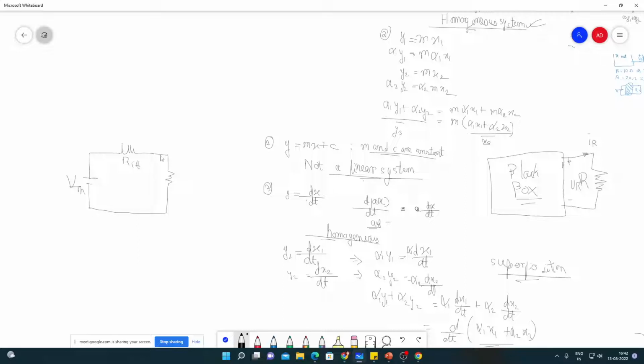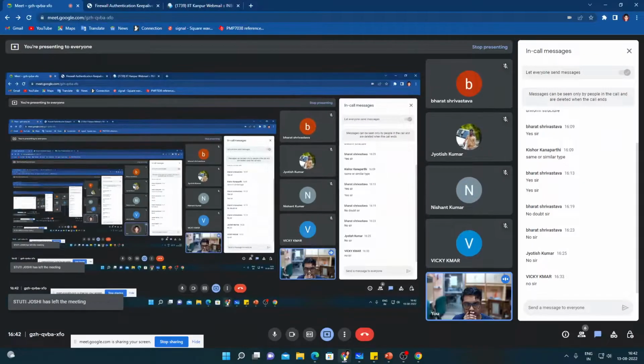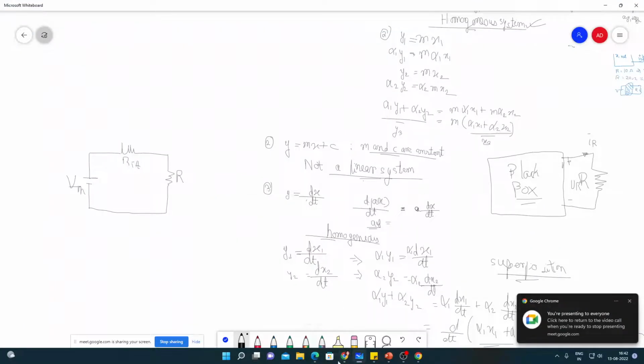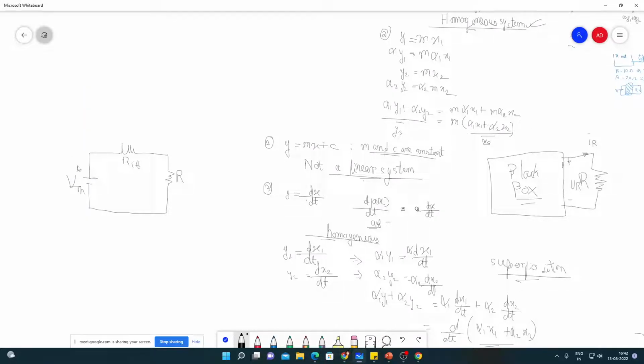We can represent it in this form. Thevenin's theorem just states this fact. Now how does it help? If you have a very large circuit and you don't have any idea how to proceed, you can just replace this black box and write it in the form of V Thevenin and R Thevenin.